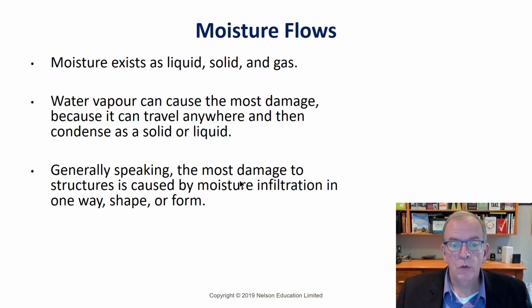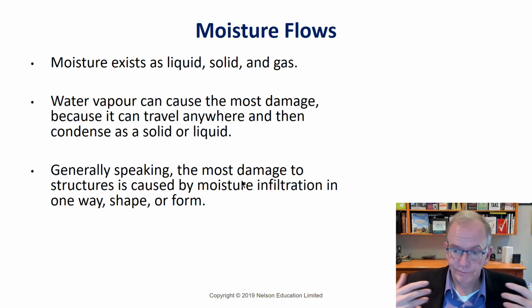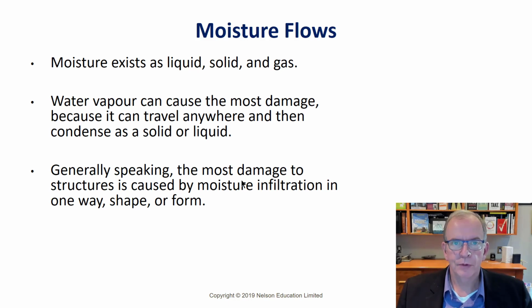Really, when we think about all of the buildings that I said, and survivorship bias, the bias towards buildings that have lasted a long time, is that most of the buildings that dilapidate and really have major problems, there's been moisture ingress in multiple ways, through the foundation, through the roof, through the walls. All of these things are trying to take the building back to nature.